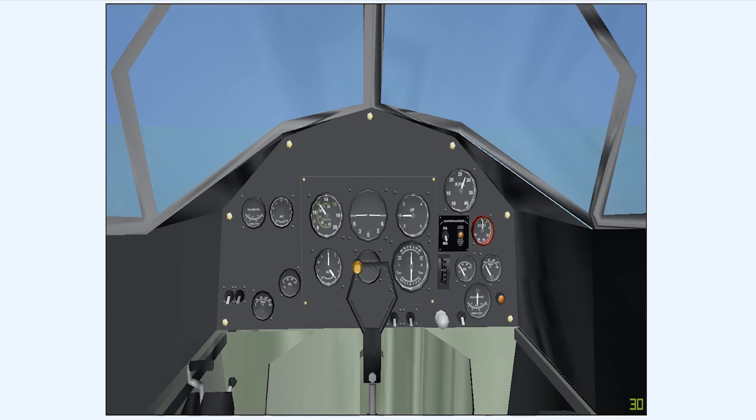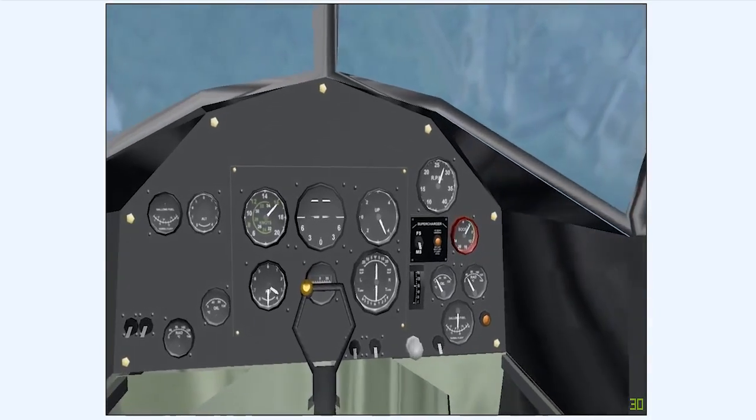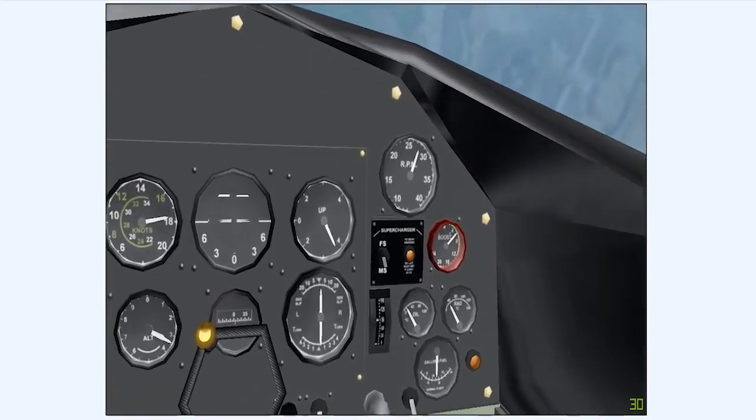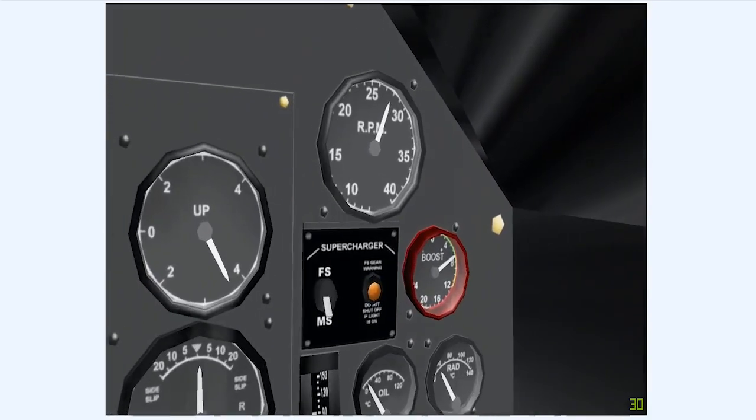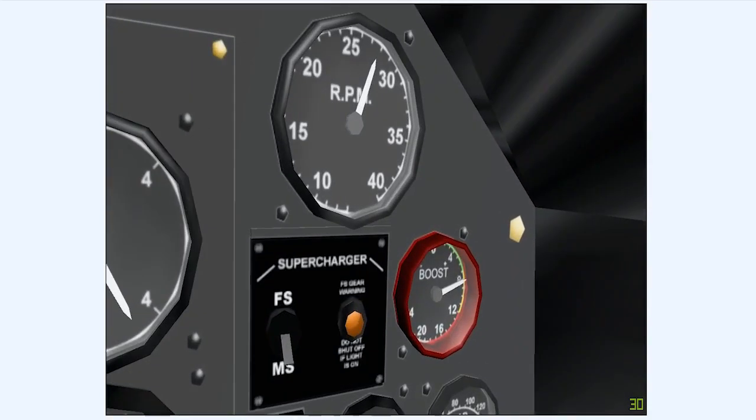Since a supercharger is designed to compress air and provide sea-level pressure or greater in the induction manifold when atmospheric pressure is low, excessive manifold pressure could be produced when atmospheric pressure increases, especially in a rapid descent like the one depicted on screen here. It's necessary, therefore, to restrict full throttle opening when the aircraft is operating at heights below full throttle height, and, to relieve the workload on the pilot, this is often done automatically.